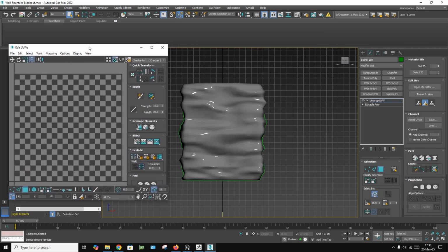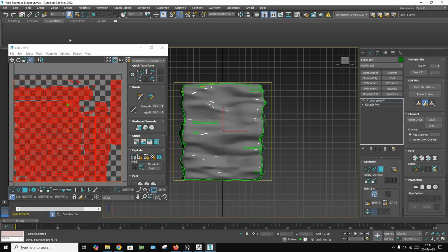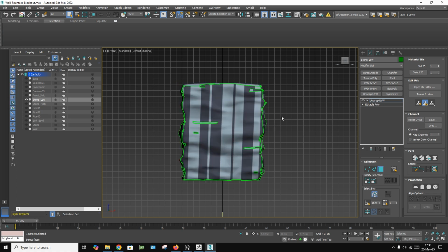Now I am going to select all of the faces, and this is a quick UV unwrapping. Later on, once we get the good result and once our test is complete in the Substance Painter, I am going to re-unwrap this properly, but for now let's just flatten this. Okay, I have installed text tools, so let's check this in the text tools.